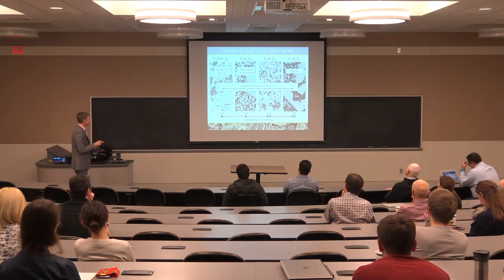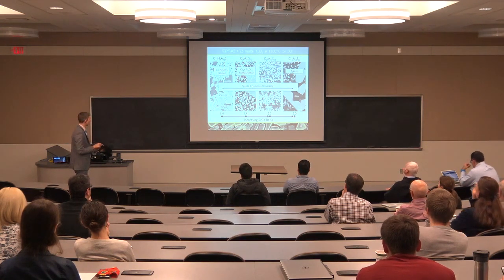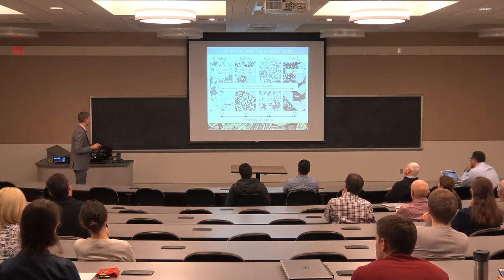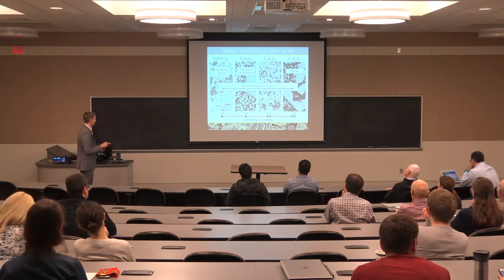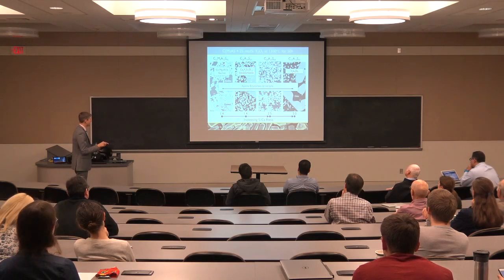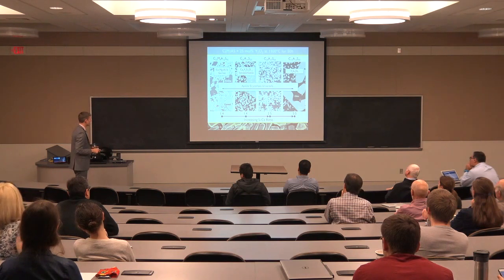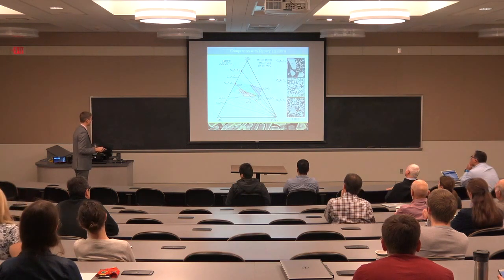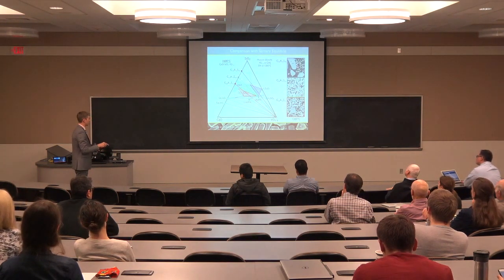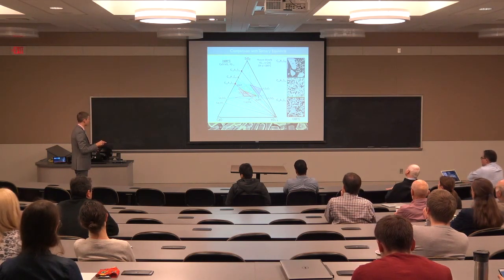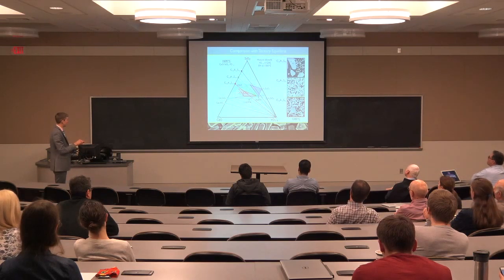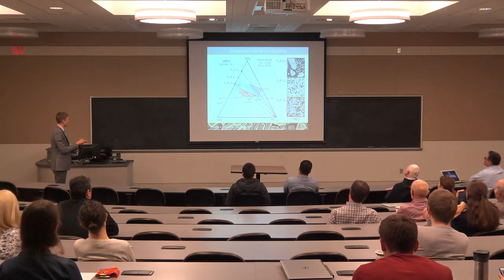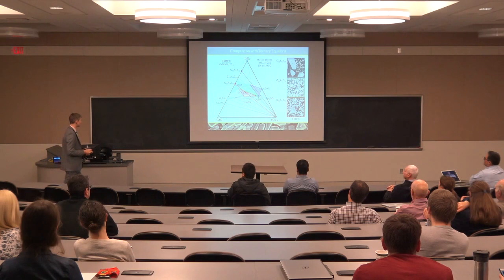When we look at these outlier cases that are further from the center of the liquid field, in this case we also precipitate out an yttrium-containing calcium magnesium aluminosilicate garnet. In this case, we get the silicocarnotite phase, and in this case, we precipitate out some yttrium silicate. So we've mapped out the extents of the phase field where we expect apatite to form. And if we map these experiments back onto this ternary section, we basically captured each of these three phase fields. In each case, we have apatite, but then we also get these other silicates in the system.